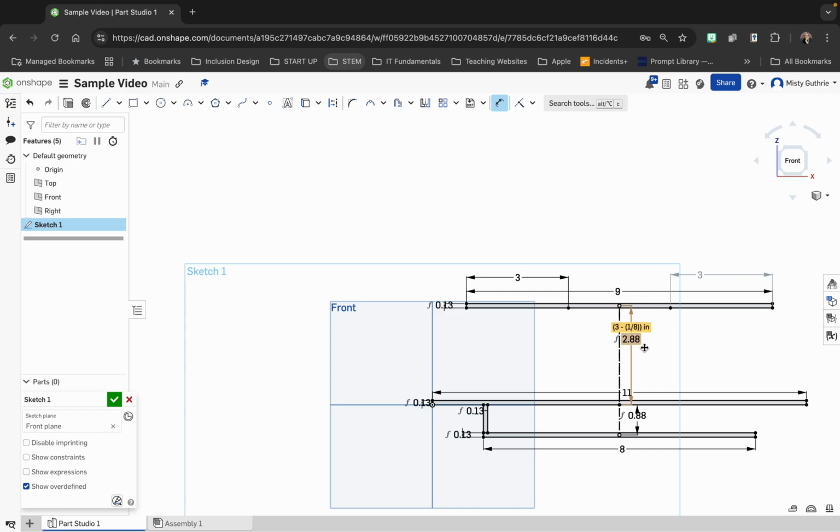So I think that it automatically just knew it was going to be 3 inches long. When it's grayed like that, that means the CAD program already recognizes that it's 3 inches, so it's really not necessary to have those in there. I'll delete them.